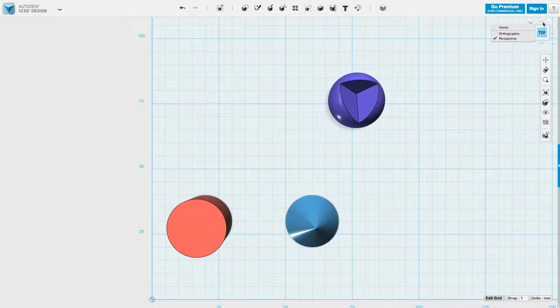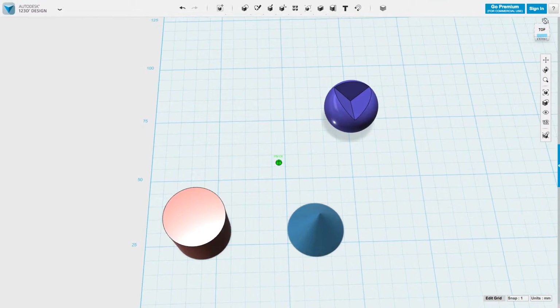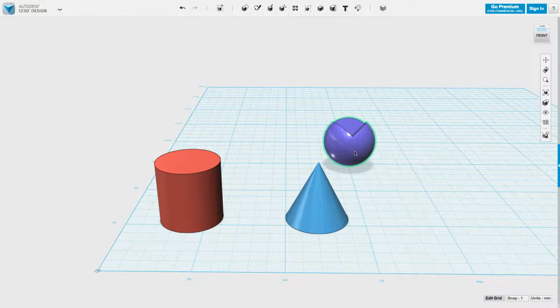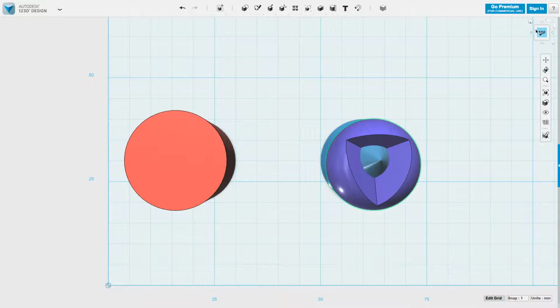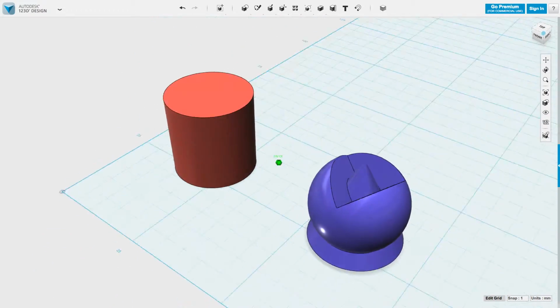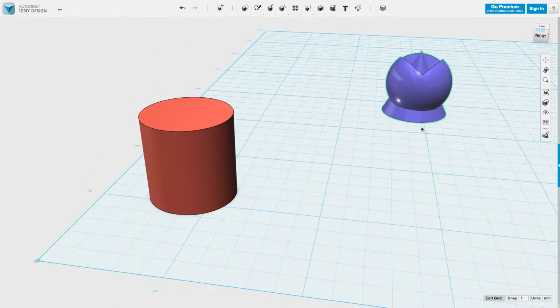Okay, to merge is very similar. Just going to find a different view. Say I want to take this guy and merge him into there and have the tip of that cone come popping right out. Oh, that's actually pretty accurate. Okay, I like that. I'll have to trim off the rest, but let's try this. So I'll go to my combine tool, select merge, and same thing, do an addition. My first solid with my second solid, and then enter. And now, because I've combined the two, it changed color because it's all from the same mesh. Now when I select and I move, they move as one.